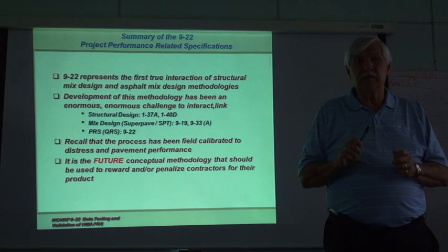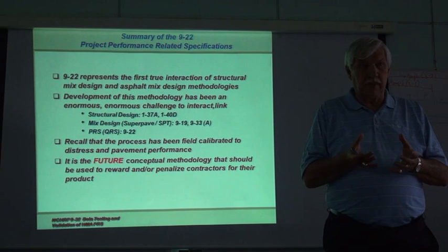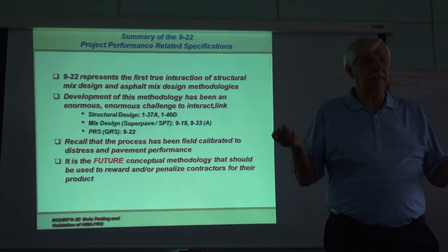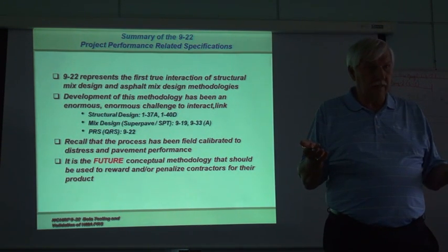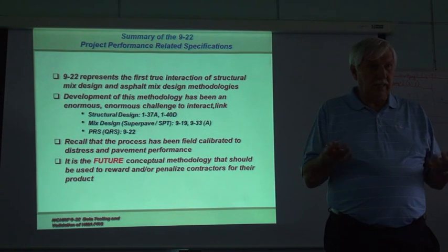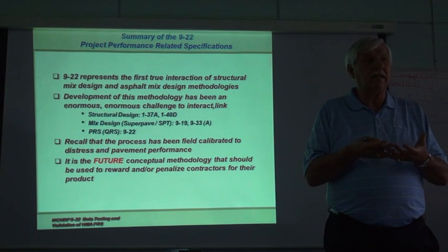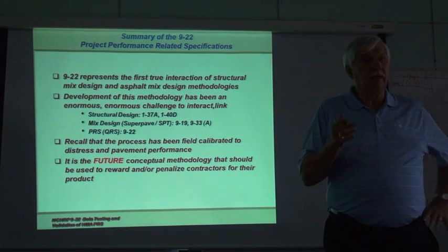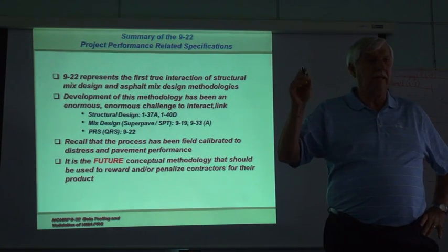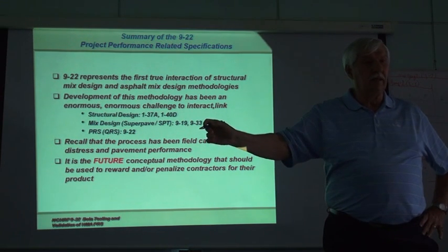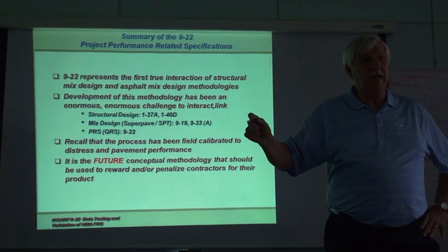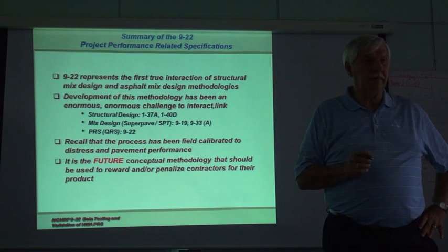I'll tell you, you're going to increase the load. Because what they're going to do is put more asphalt in the layer in which I'm going to be getting my extreme fatigue cracking. And as a result, the greater the bitumen volume I have, the less likely I am to fatigue. So in practice today, we'll penalize somebody for putting in a little bit too much asphalt, but in reality, he might be extending the life of the road.